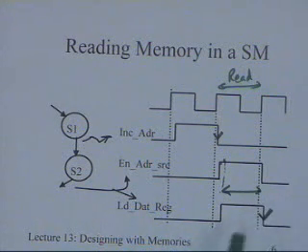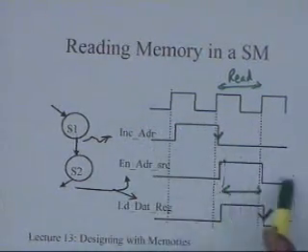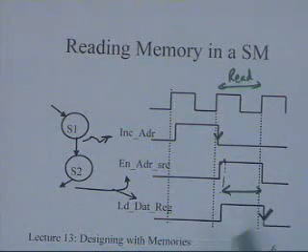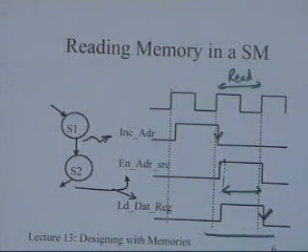So basically if you look at it, you can just do it in one clock cycle. As far as the timing for this memory is concerned, there is not much required over here. This is all again related to how the address is generated. This is also related to the enable address source. The only thing is the read has to be high. You can also associate a read signal with this particular edge where it is actually high for this particular duration.